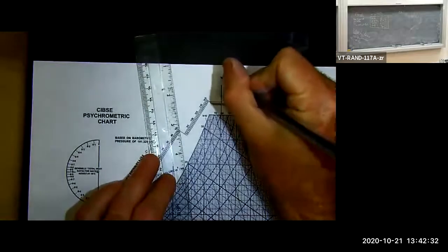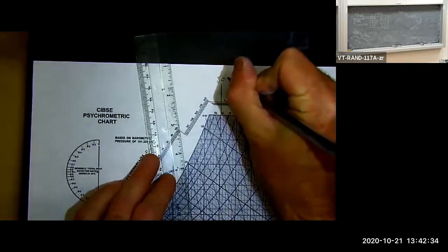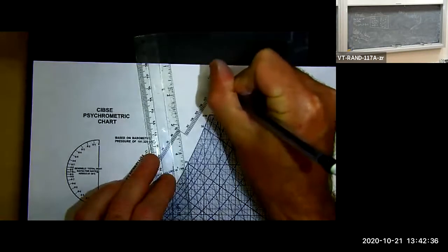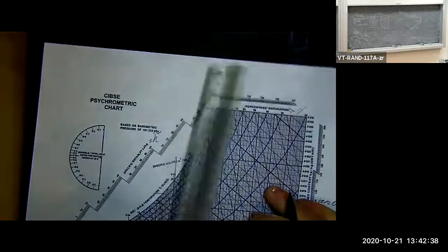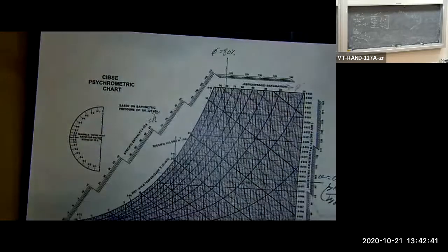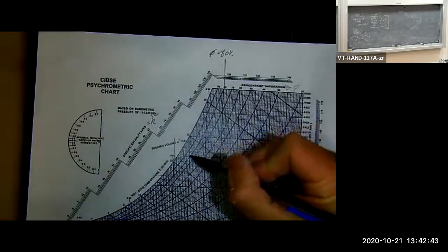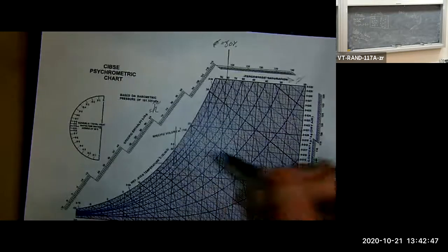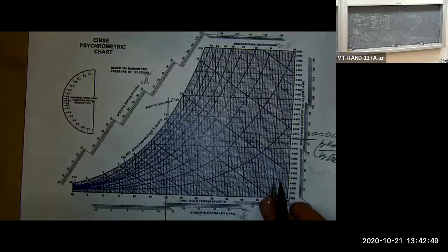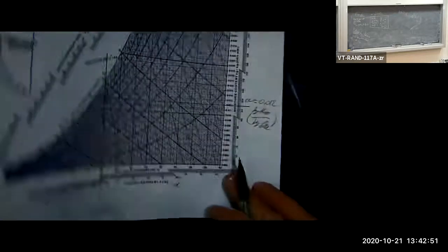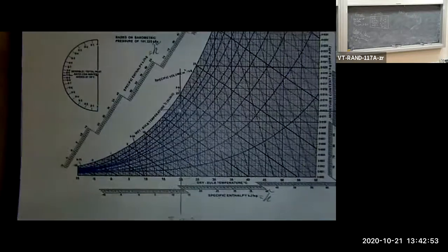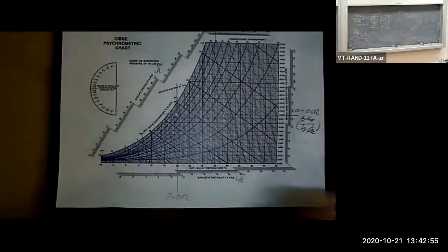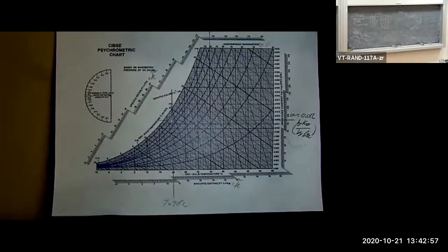So this is 80% relative humidity, okay? Puts us on this line of constant relative humidity. The intersection with my 20-degree isotherm gives me the absolute humidity. I think I can back out a little bit now that the resolution is improved.